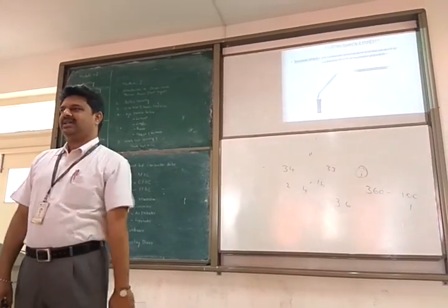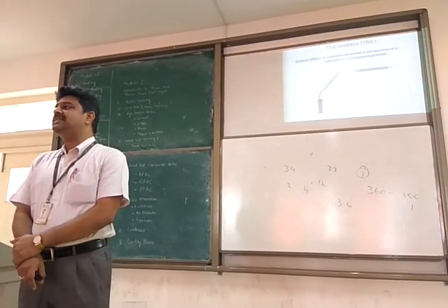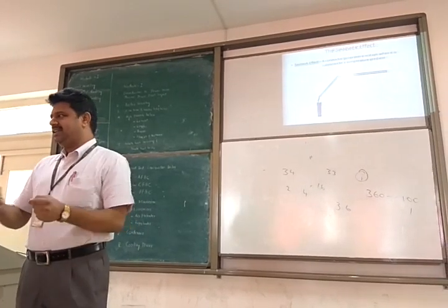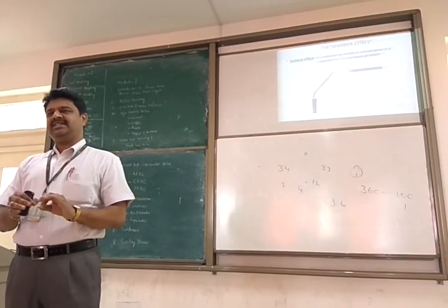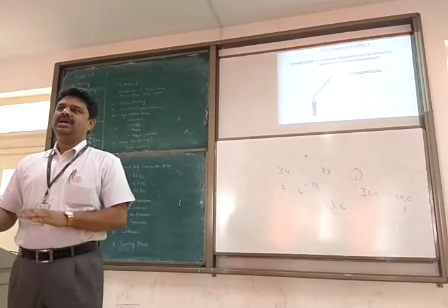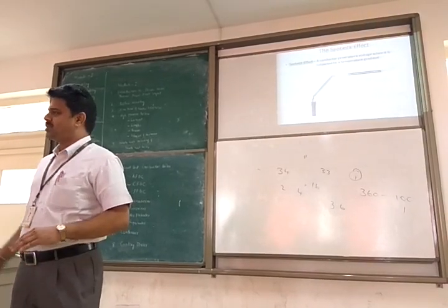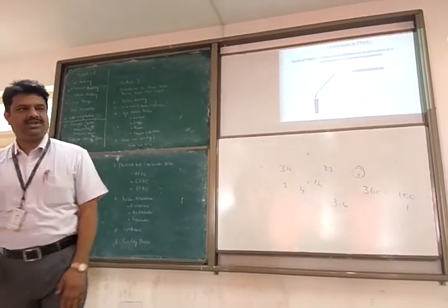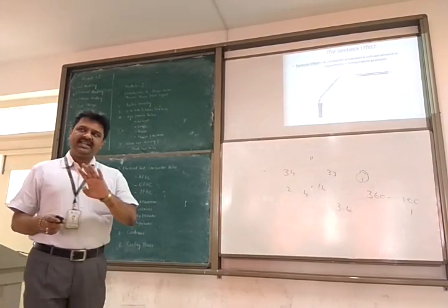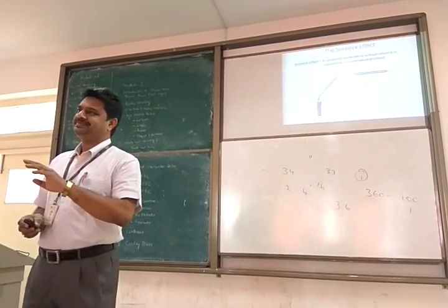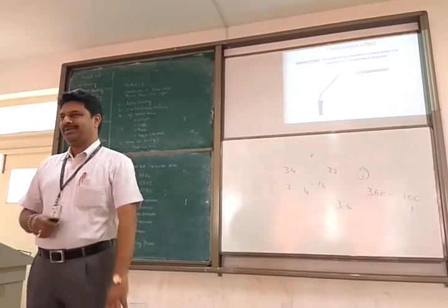If the resistance value decreases, then it is a thermistor. Otherwise, the change in resistance is proportional to the temperature. By measuring the change in resistance using a Wheatstone bridge, you measure the temperature. So RTD and thermistor both work on this principle.